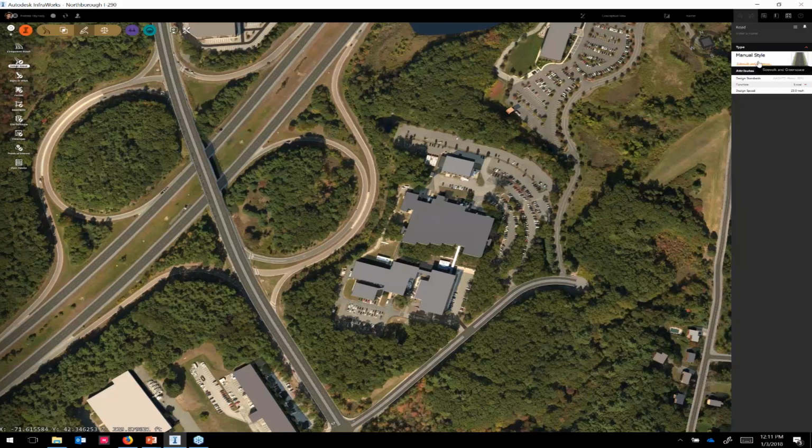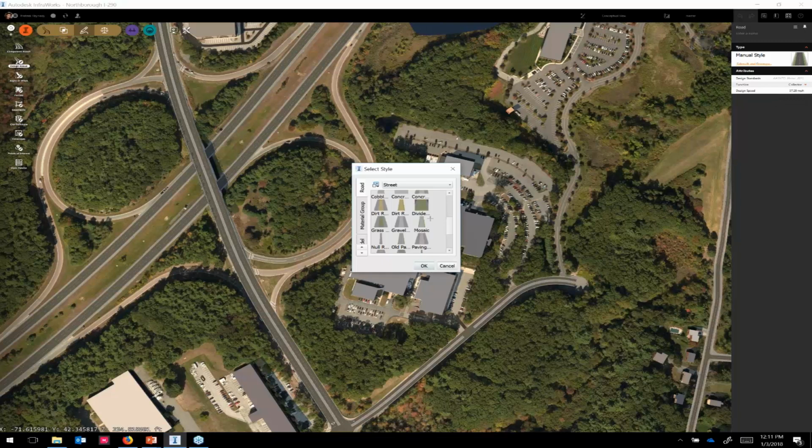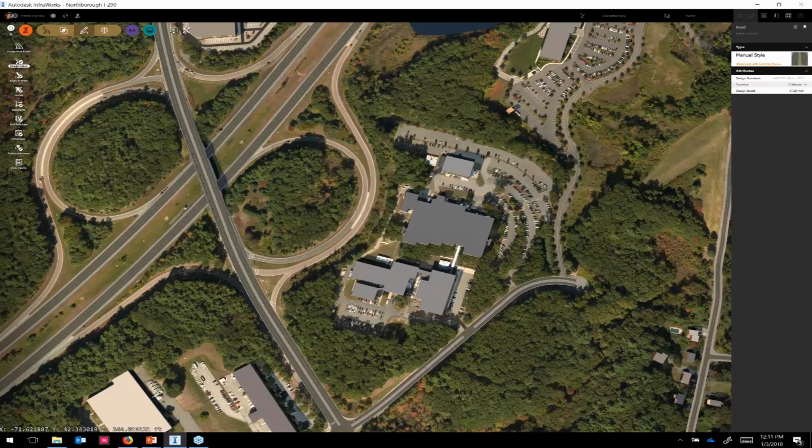So the functionality that was provided by those different icons could still be achieved by going in here and changing the function and setting a new design speed if you need to. If I wanted, I could still set this up as a 50 mile per hour road, change the function to, say, collector, and then also change the style of road that I'm trying to lay out. Say boulevard, and I'm just going to bulldoze through this section.